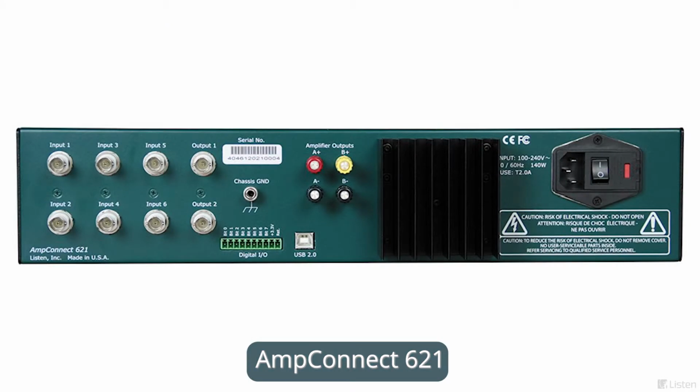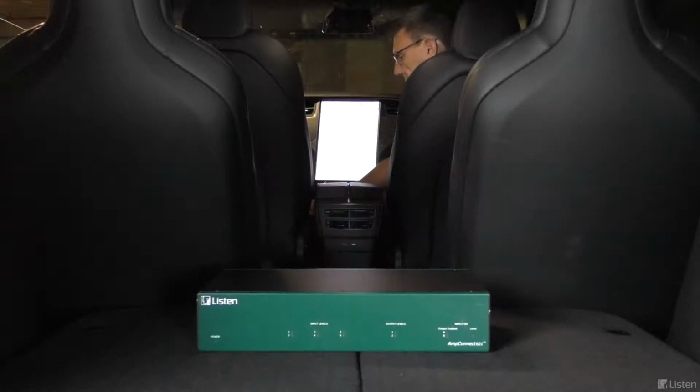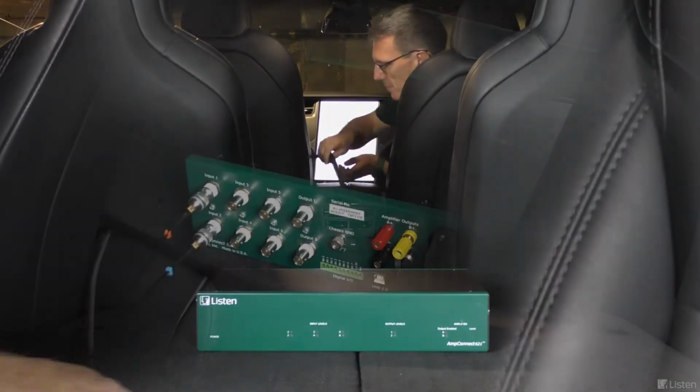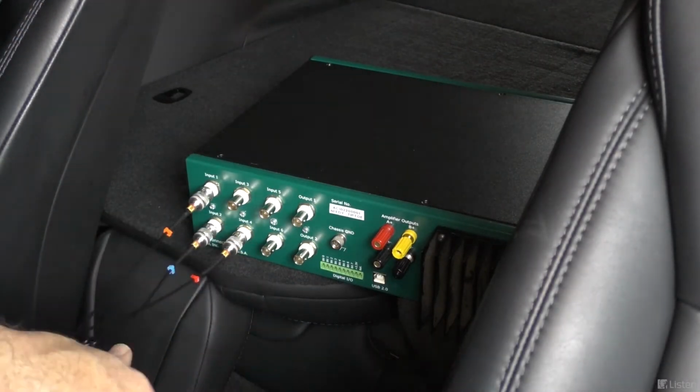This one is particularly good for automotive tests because it has 6 input channels which match up with the 6 mics. And all channels offer mic power. It's also TEDS compatible, so if you happen to have TEDS microphones, you can save yourself some setup and calibration time. Now let's plug the microphones in. And I'm going to connect this up to my computer using the USB cable.